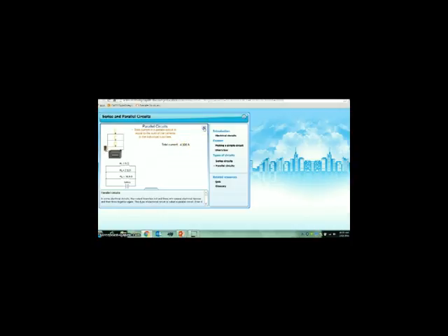Now, if you measure the current of the first branch, note down 2 ampere, second branch is 1.6 ampere, third branch is 0.72 ampere, and if you sum them, you get the current as 4.32 ampere, which is the total current you measured before. So it is the current which gets divided here. So current division is an important operation inside parallel circuit.